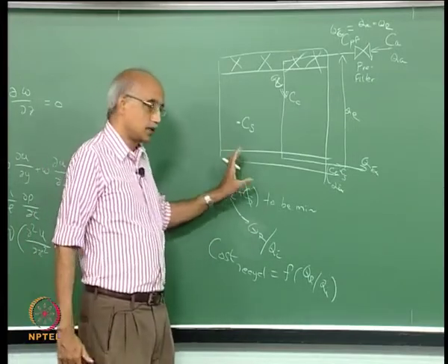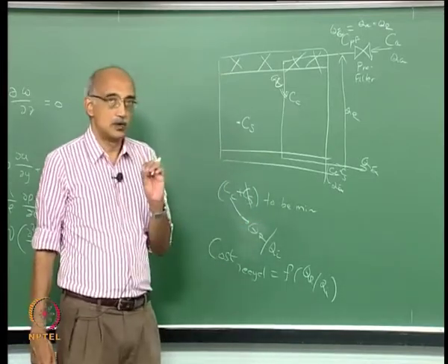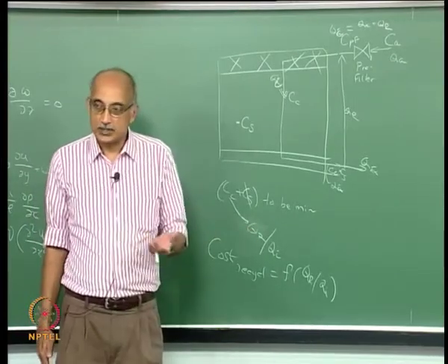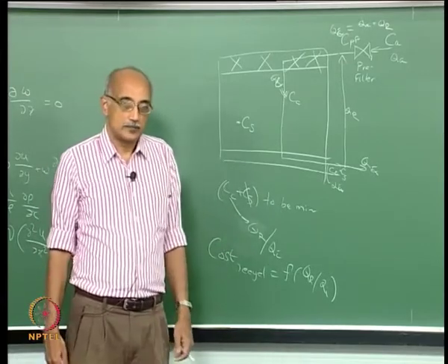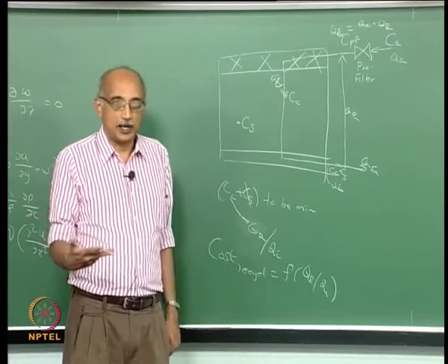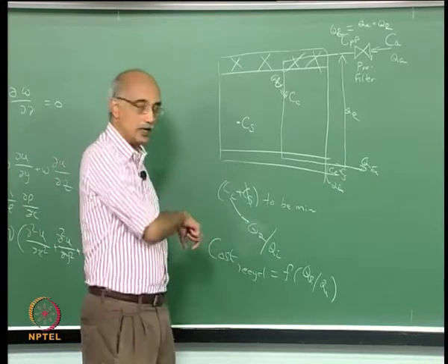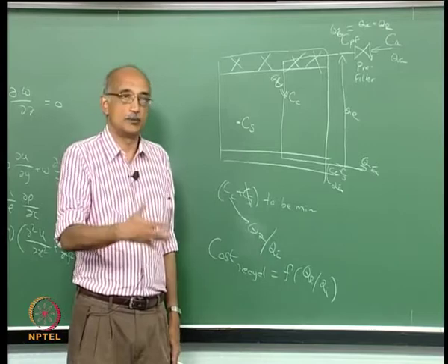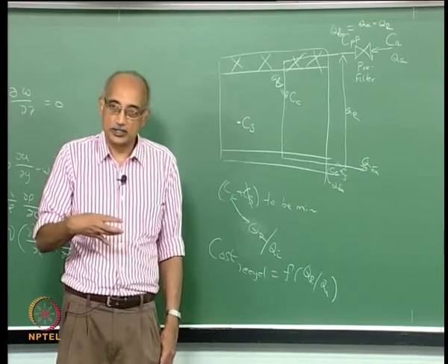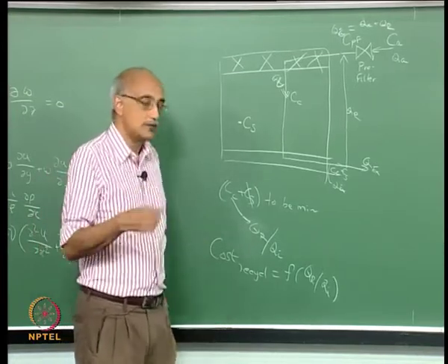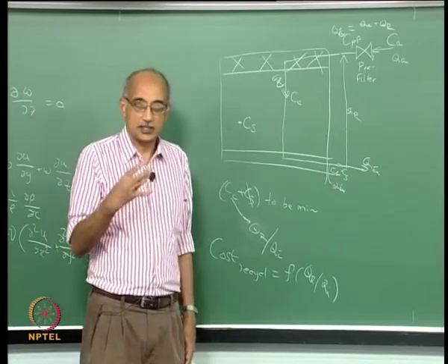So the first part I think is something that you can do separately as a minimization exercise, and it'll give you a value for QR, which gives you a minimum in Cc, and then if you're given this number about cost of recycling, and you're given that something is the maximum that you can afford to pay, then you can compare your optimum value of the recycling rate to the maximum value that's allowed from a cost viewpoint and ensure that you're below that level. If you're not, then you have to operate under suboptimal conditions. You have to reduce the amount of recycling and perhaps live with a higher Cc value, but with a correspondingly lower cost. So that's a kind of exercise that clean room engineers go through.